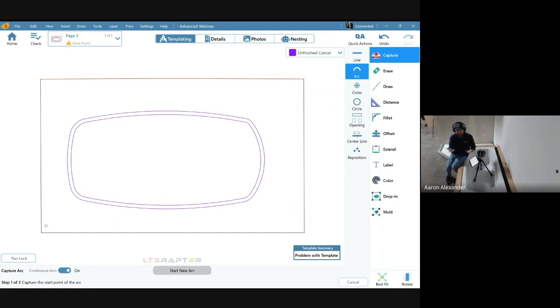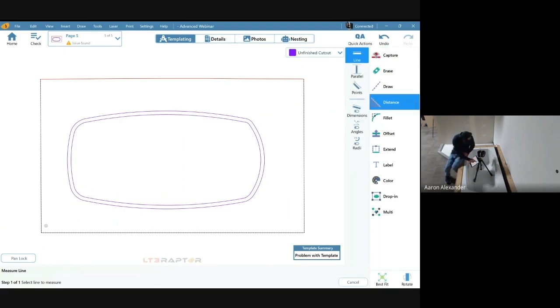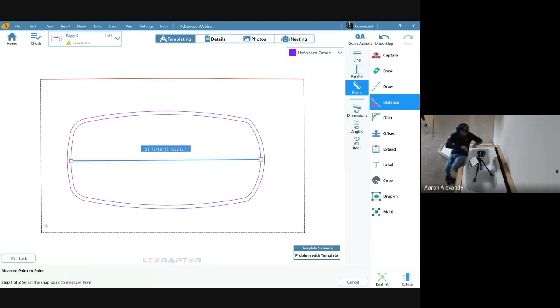Now, where are we going to spend time in creating this cutout right here? As you see me, I'm spending my time here on site, nailing these tangents, seeing the transitions, and making sure before I move my laser out of here, that thing looks pretty. It's looking good. We can come in distance, we can do points, and we can measure across this thing. You know what I mean? Pull some tape, check this thing out, pull from the center of there to the center. That don't really line up. But you understand, we can get some dimensions to verify things, right? To make sure things are in the right spot.